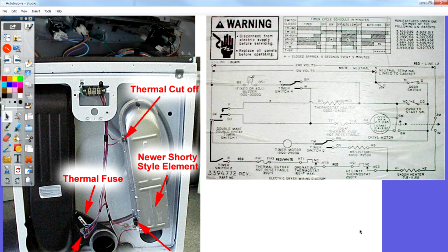So one day if you run across a machine you've never seen before, you can say, oh yeah, that's just the high limit thermostat. That's the operating thermostat because of this. That is sort of what I want you guys to work towards. Not just this Whirlpool dryer, but other brand dryers, the same components. Because all dryers have a heating element, except for the gas ones.